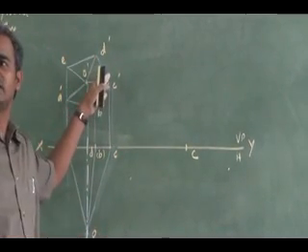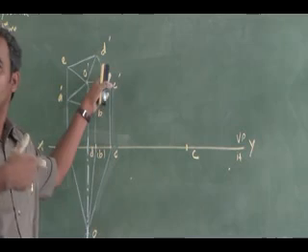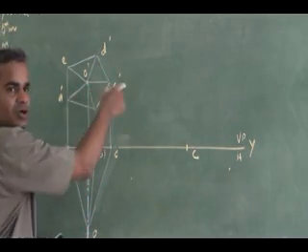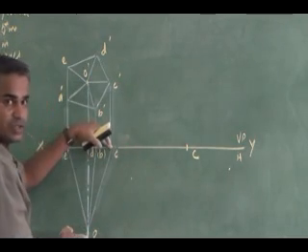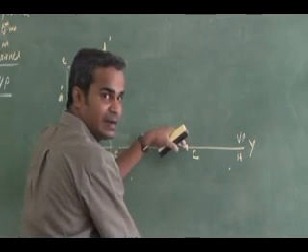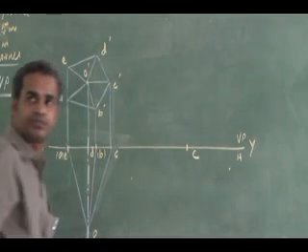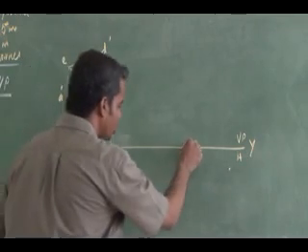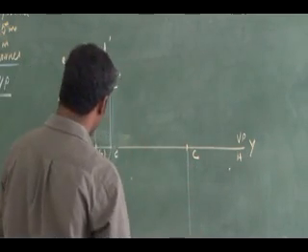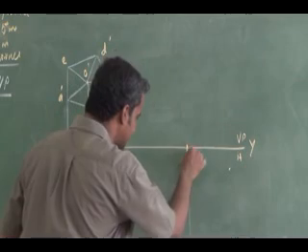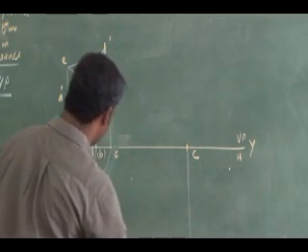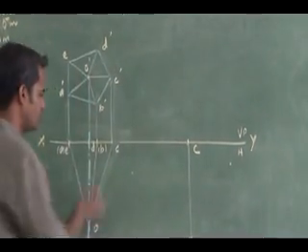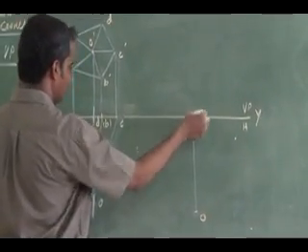What about in top view? That is a straight line. That line is nothing but CO. A CO line, I have to make it as a straight line in my final top view. So you measure CO and draw it as a straight line. So that is my CO. Then you reproduce this front view.